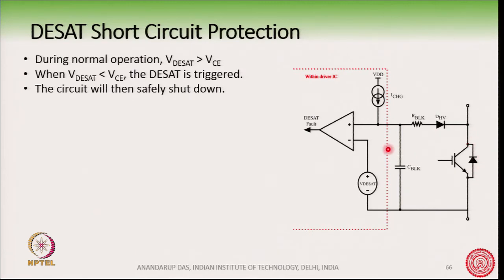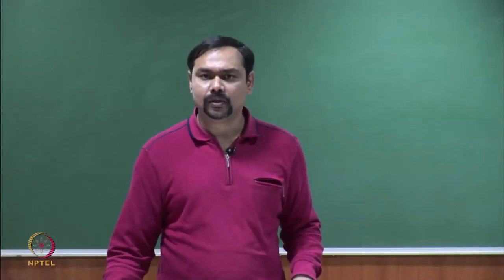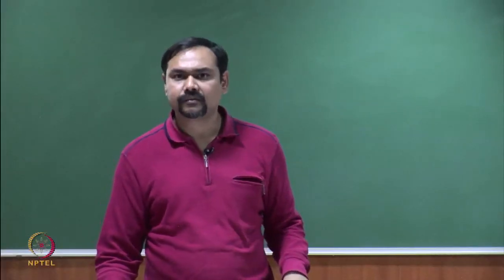If you do not use these components, every time the IGBT is turning on, it goes from the VDC voltage to suppose 2 volts, which is the VCE on of the device.